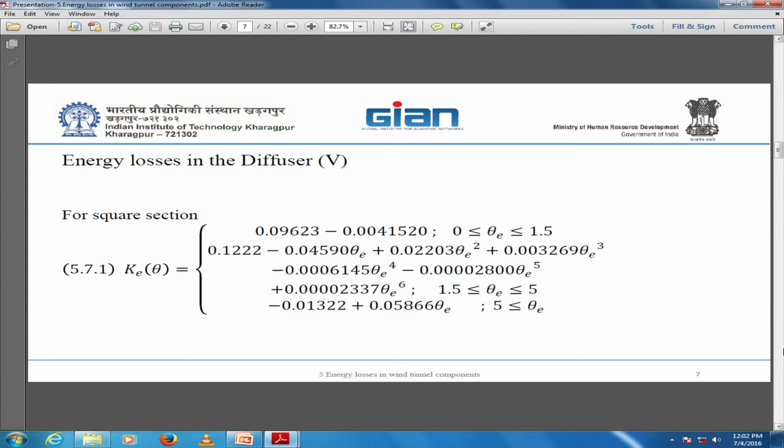So the angle of attack you decide based on CFD? Yeah, you can work it out with CFD. But usually, you see so many designs recently, and some people were really investing in checking all kinds of setups. The one we picked in Tel Aviv, this 4 degrees, the fellow was measuring the velocity distribution in such a setup, and he got a really good uniform one. So we just took that one. I think it's somebody from Sweden, I'm not sure.